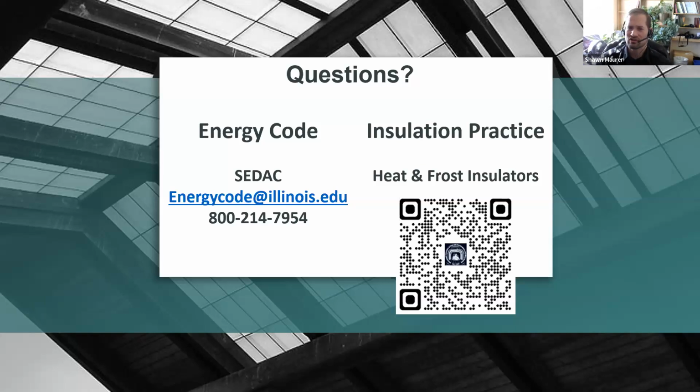Sometimes those performance requirements are going to be priced out, like when we're talking about stud wall cavities. You don't want to build a 20-inch stud wall to meet the R30 or R20 wall requirements in the current code. So if you want to stick with a typical 2x4 framing, you're going to be working with more continuous insulation on the outside. So in that regard, the code might push one type of application over another.